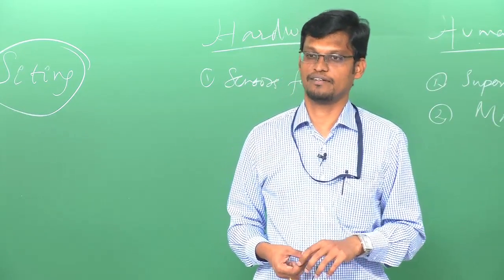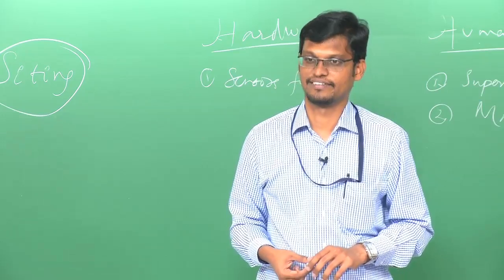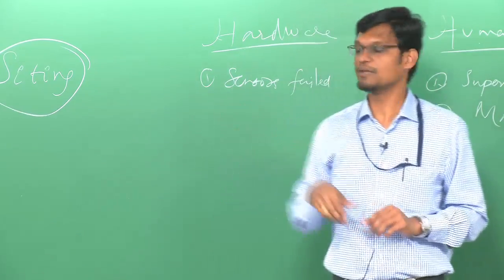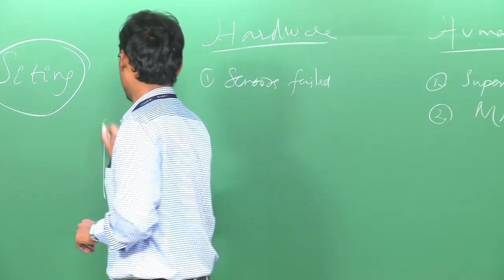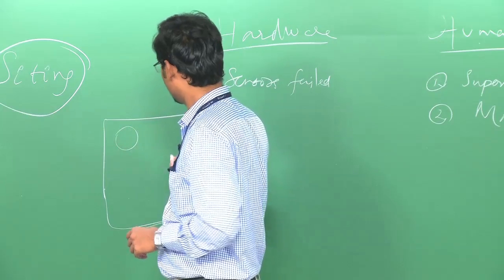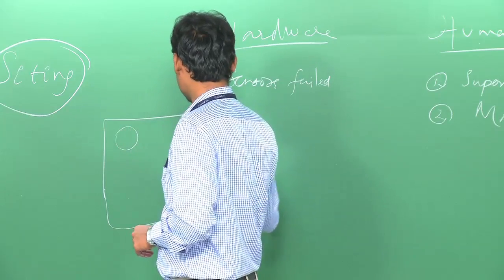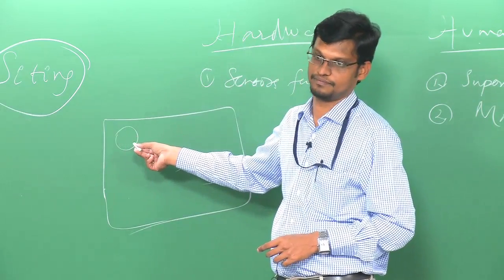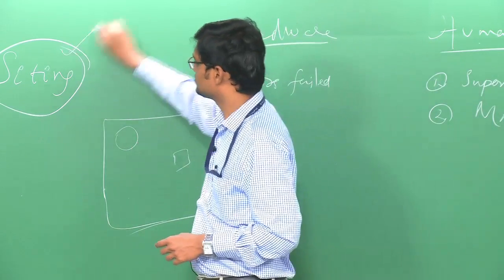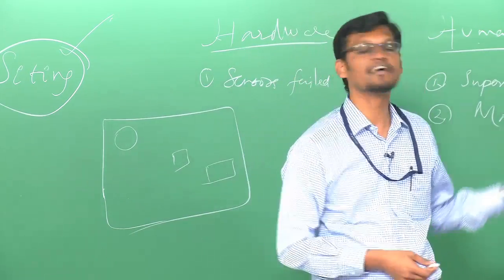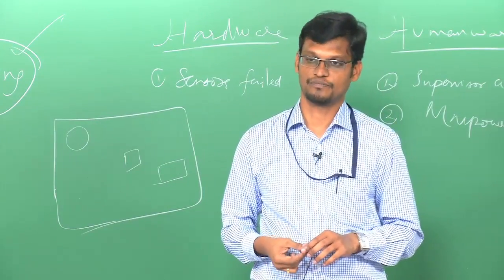Not only equipment, we talk about the overall process blocks. Okay, you have an industry, you have a layout, you have storages here, you have a control room here, you have process blocks here. Now, which should come where is what siting talks about. In fact, there is an API standard on siting. Post this incident, the standard itself was reviewed.